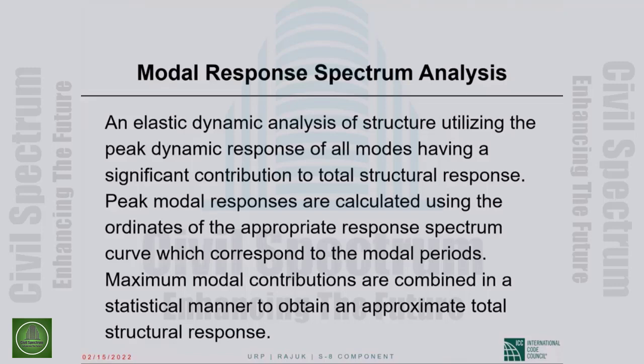Peak modal responses are calculated using the ordinates of the appropriate response spectrum curve, which correspond to the modal periods. Okay, so you have modal periods. You go to your spectrum, and you see the response quantity. Spectral acceleration, spectral velocity, whatever.